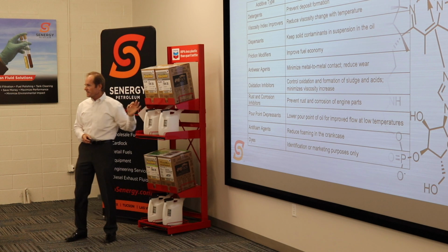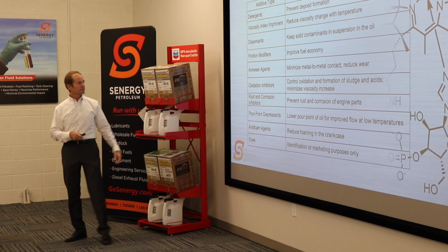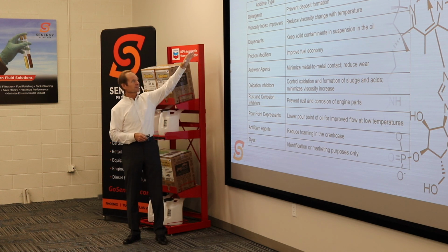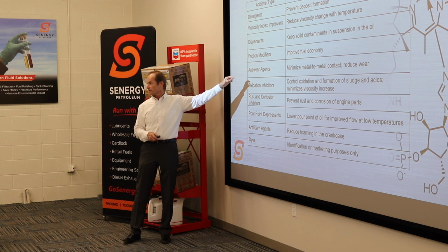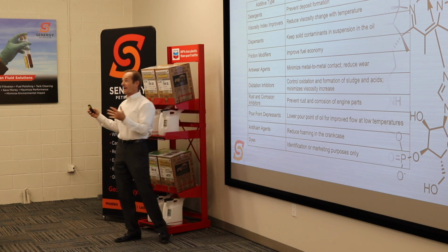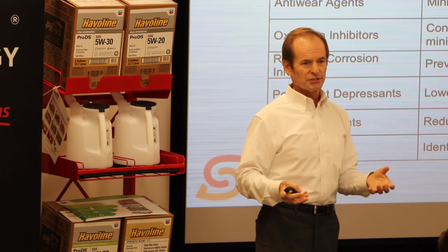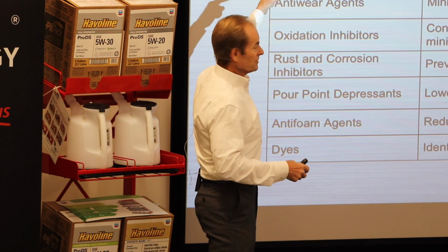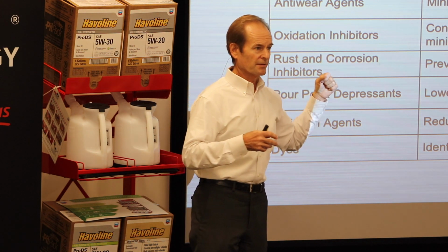And within each of these, there are usually at least two and sometimes more technological approaches for how you do it. There are 3 or 4 different types of viscosity index improvers. There are half a dozen different kinds of detergents. There are at least 3 different kinds of anti-wear agents that can be used. And that's why different companies have different engine oil formulations. That's why not all engine oils are the same, because depending on which of these you've chosen, some function better in some ways, some function better than others.